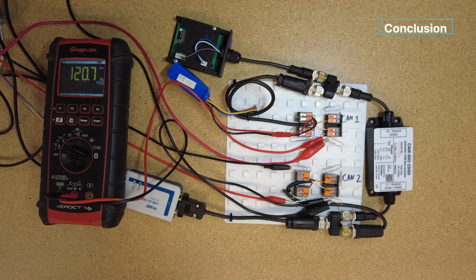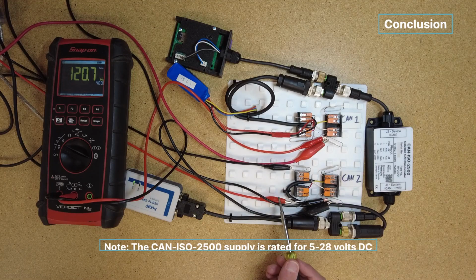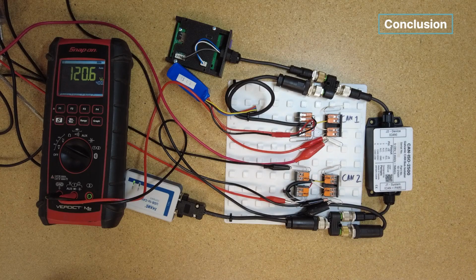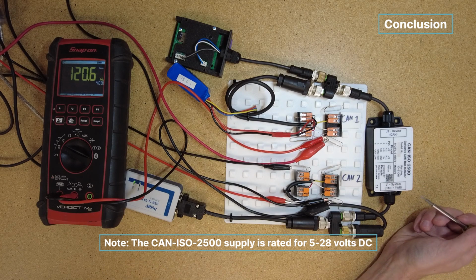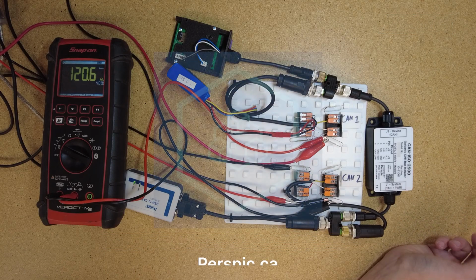If you have a battery electric EV kind of application, or any application where you have a main network supplied with anywhere between 5 and 12 volts DC, and you have a secondary segment of the network that you want to be seeing the exact same CAN messages, our CAN bus isolator will help you do that. And in this demonstration, we went up to 120 volts DC, but this device is rated for up to 2,500 volts, AC, DC, or transients. It'll stop them all.